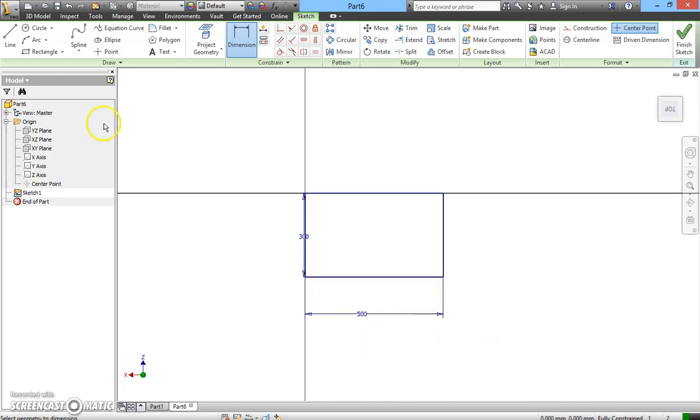Next, I'm going to use the line drawing tools. Draw a perpendicular line from this surface. Click on it, drag it out, make sure it's 90 degrees. Click, and then I'm going to make sure this line is perpendicular to this line. I'm going to drag it until contact and click on it.